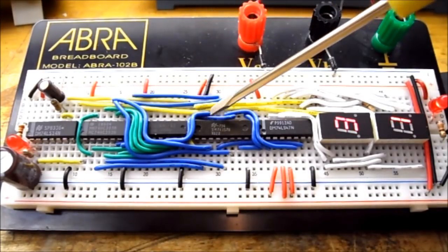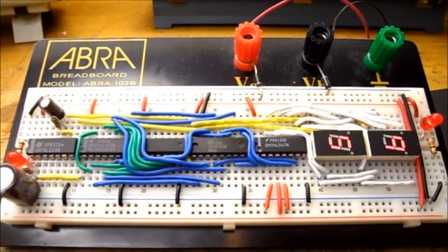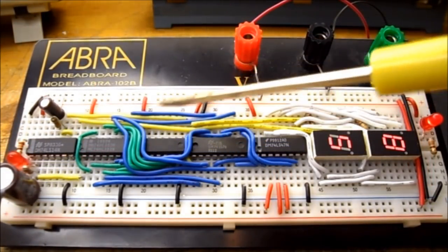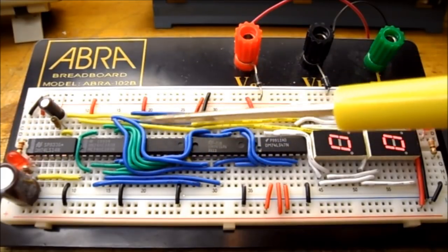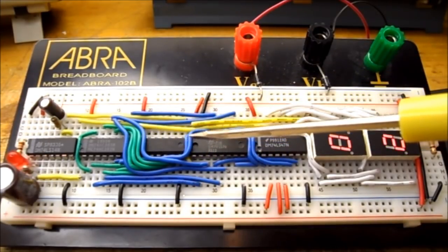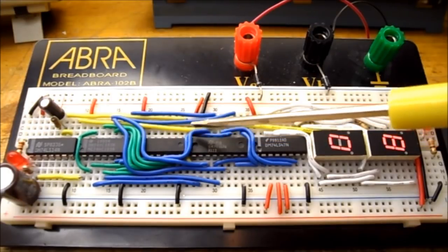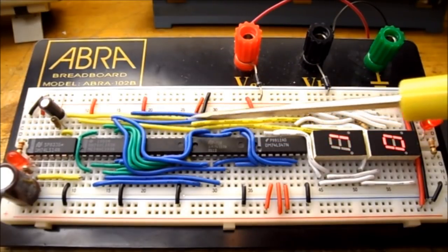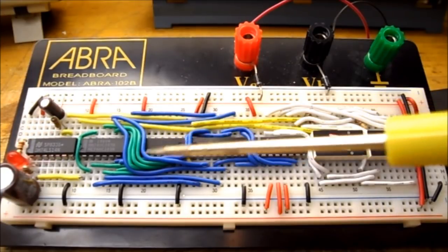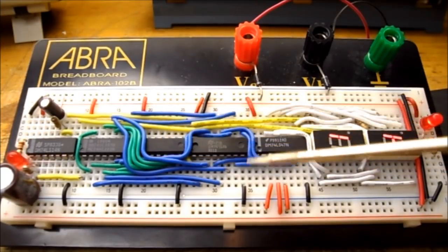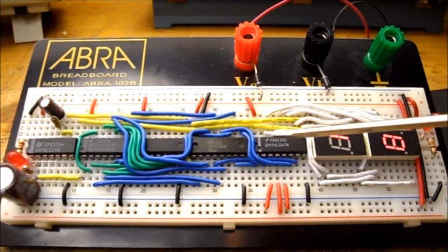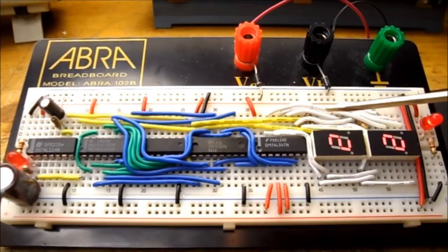I have all my ICs lined up here. One of the things to note about this circuit is even though it is a fairly complicated circuit to wire up, if you put them in one line at a time and highlight each line that you've put in, you shouldn't have a problem wiring up the circuit. It's also important to keep your lines as neat as possible. You don't want a whole jumble of wires running back and forth across all the ICs, and then you can't see if one has fallen out. So keeping your circuit neat is the trick to building a successful project.